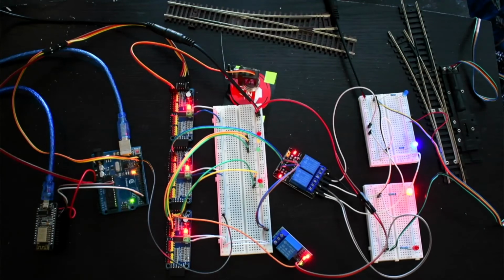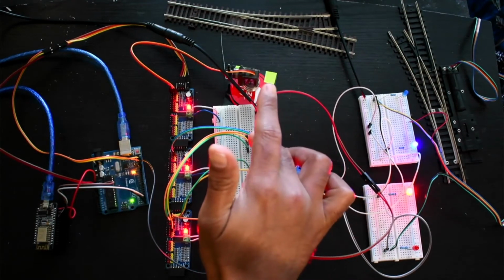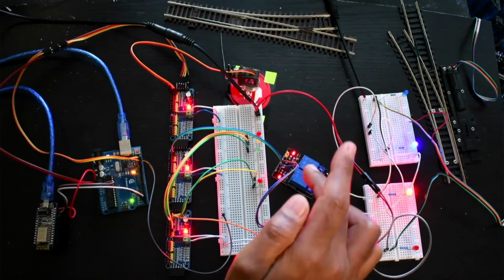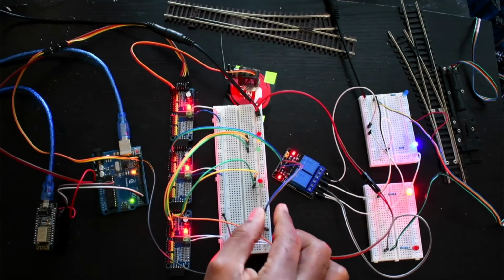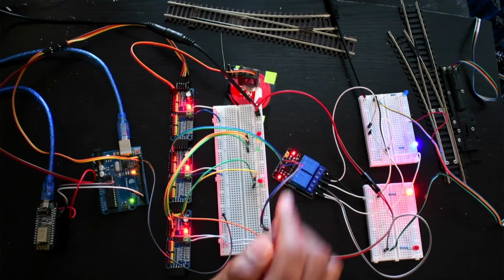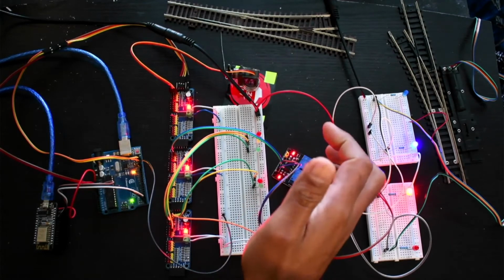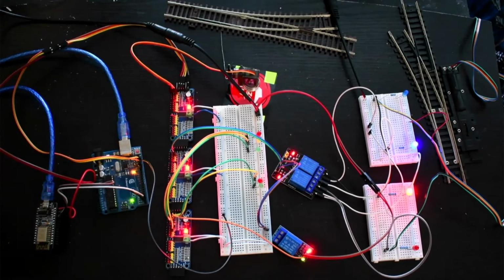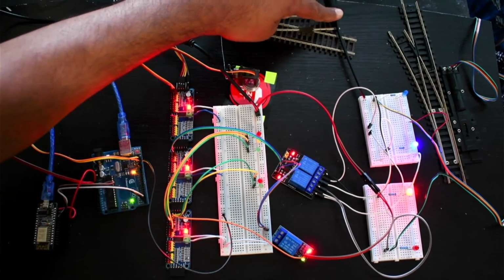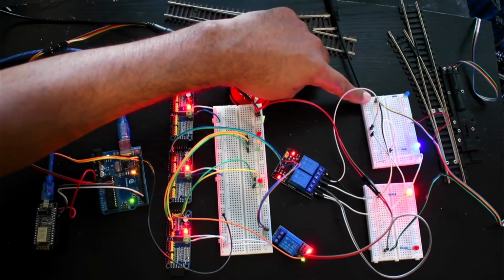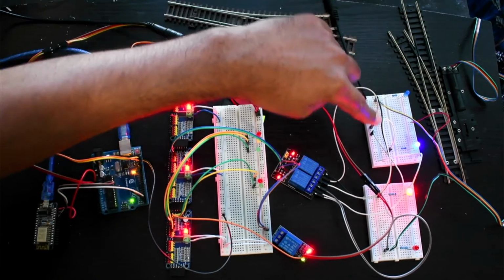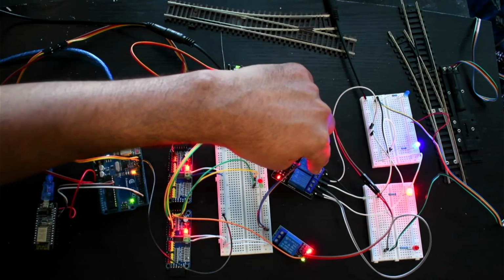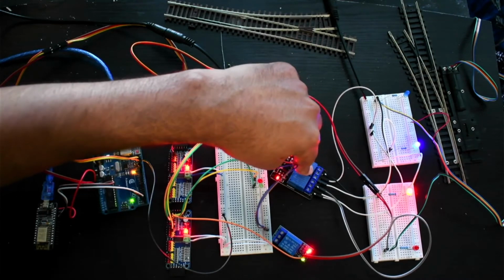So here you can see this relay switch is taking signals from board number 1, from this blue wire, and from this brown wire it's taking 5 volt from this breadboard to this relay switch. And this relay switch has an external 12 volt power supply coming to this breadboard. From this breadboard, these two wires take the 12 volt to the central pin of the relay switch, which is the common one.